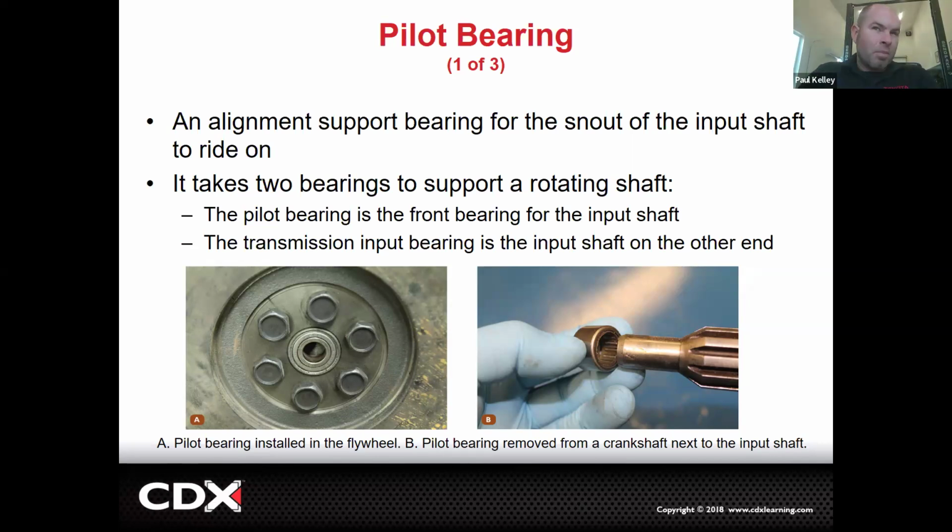If you were a different type of backyard mechanic and you were trying to use bread, let's say, for example, Bimbo white bread maybe, and you stuffed a bunch of bread in there and did the same thing, that bread will actually function the same as the grease. You'll hit the bread in and the bread will mush out, like it'll go back to sort of when it's doughy, and it'll actually drive the bearing out. So if someone says, oh, I get my pilot bearings out using bread, it's kind of a joke, but they might actually do that.